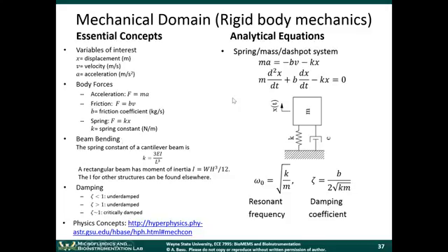You can add all those three things up. So the force in the upper x direction, the acceleration force ma, is equal to negative bv minus kx. This is the force from the frictional force, and this is the force from the spring. You can express that as a differential equation: m times d squared x over dt squared, where x is the displacement, plus b dx/dt plus kx equals 0. dx/dt is velocity.